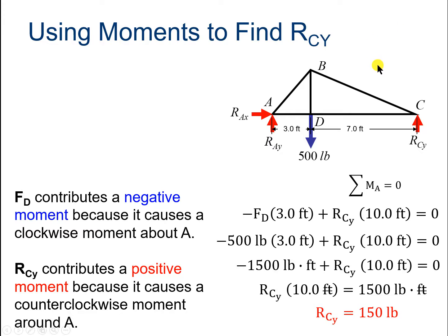This is our statically determinate truss, and we know that because over here at point C we've only got a reaction force that goes straight up. We don't have a reaction force that goes horizontally as we do over here at A. The notation can become a little cumbersome. We want to identify each joint on the bridge with a letter so we can tell them apart, but then we need some subscripts to tell where we are.